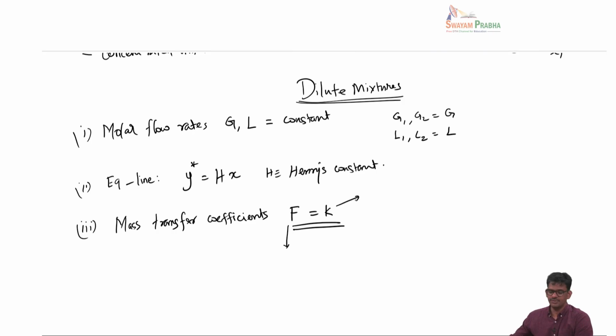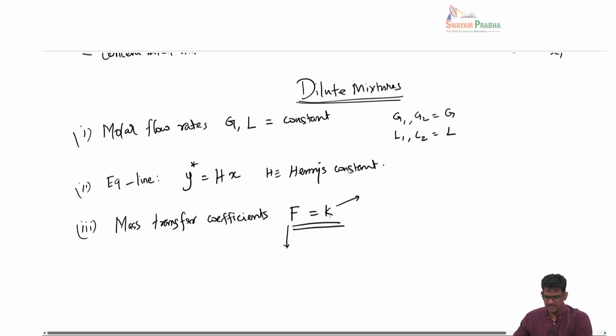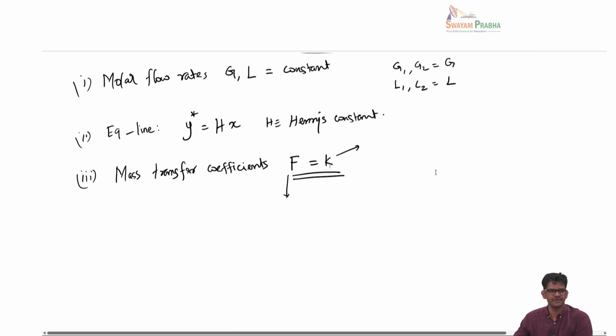Okay, this was something I demonstrated in one of the previous classes on mass transfer, interface mass transfer, but we can also see it here. So let's say if you have an F type mass transfer coefficient, you generally write the mass transfer rate as 1 minus yi by 1 minus y.